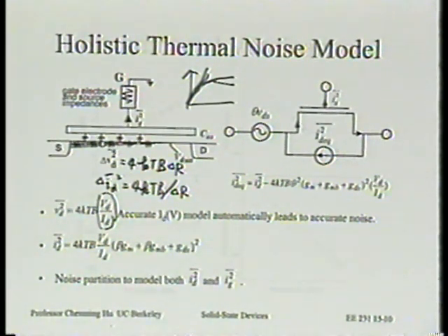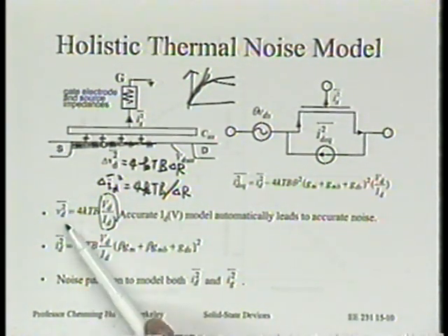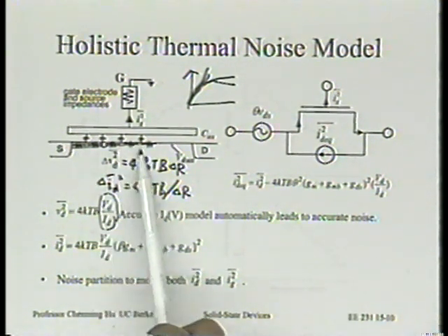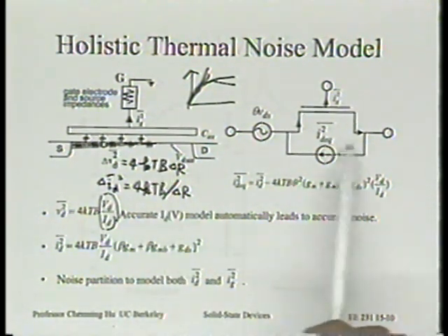That would be an interesting argument. But in reality, if you look into this, this is how you relate the noise voltage to noise current. It turns out you want to think this way. There are several reasons this noise voltage is going to produce noise current in the channel.